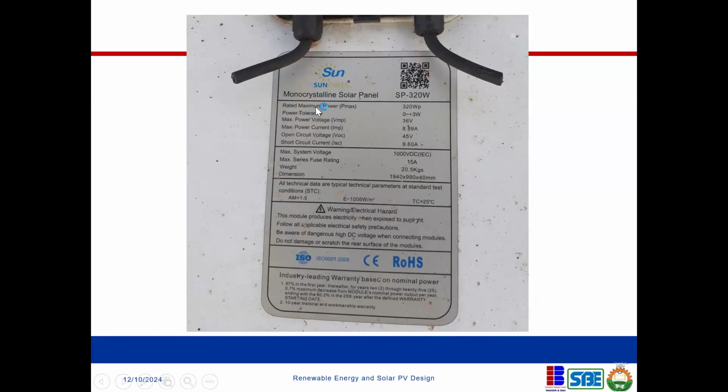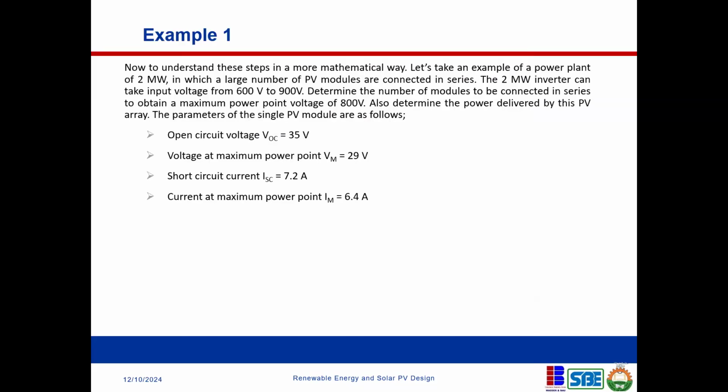And I took time to explain all of this in our first class so that when you see them, you understand what they mean, what short circuit current is. Short circuit current actually means the current when the voltage is 0. This is going to be the short circuit current, and it's always higher than the maximum power point current. So let us do an example. I hope we have time to finish this.